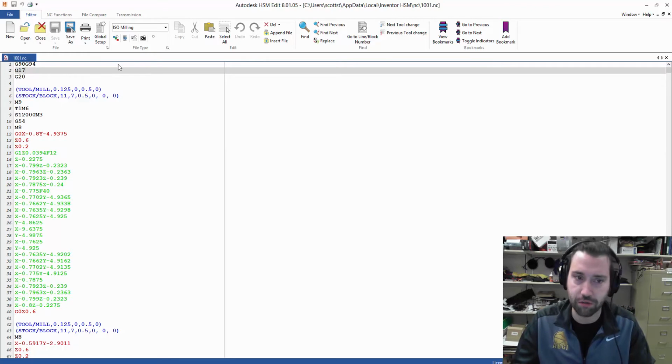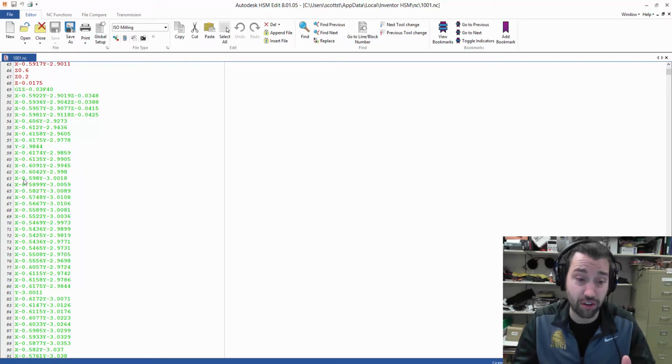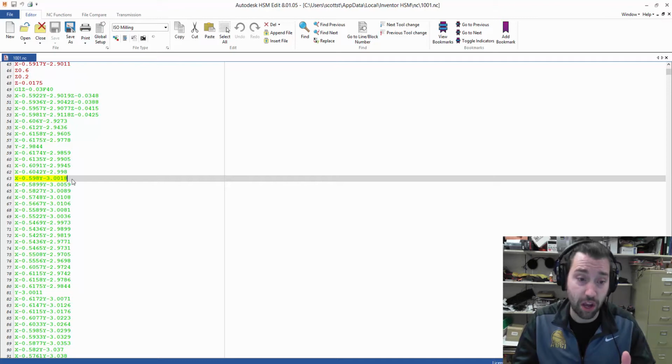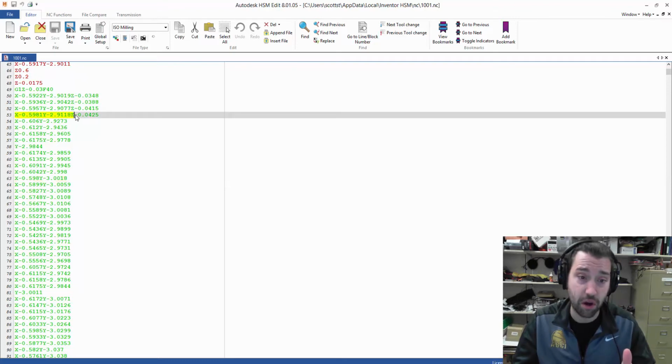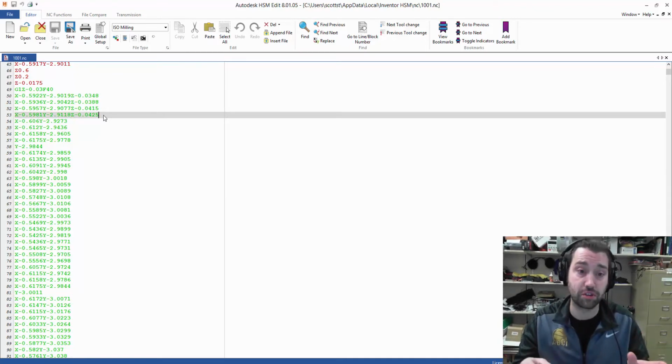And that's what I've got pulled up here actually for a sample part. I created a bunch of toolpaths and generated a .nc file, and this is G-code that our CNC router can read natively. So we basically will import this, and it's a series of instructions. We're not going to go into exactly what's going on in this file, but instead the steps that it takes to make it. But if you take a look at it, you can probably guess what some of these instructions are. A lot of them have an X and a Y coordinate. Some of them have an X, a Y, and a Z coordinate. And these are just positions that it's moving the milling bit to carve that larger shape.